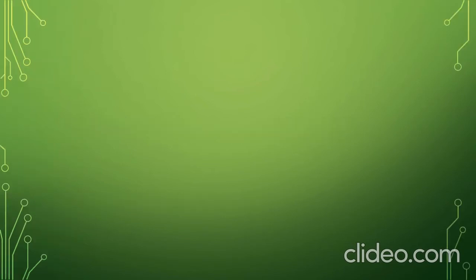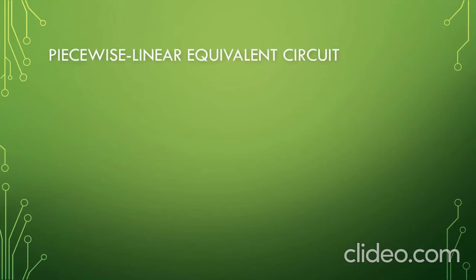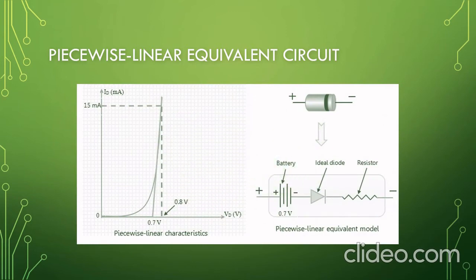First topic we cover in this section is the diode equivalent circuit. First is the piecewise linear equivalent circuit. This is the graph, this is the piecewise linear equivalent model, and this is the piecewise linear characteristics of a PN junction diode. There are various techniques for obtaining an equivalent circuit for a diode, and from these straight line segments, the resulting equivalent circuit is called the piecewise linear equivalent circuit.